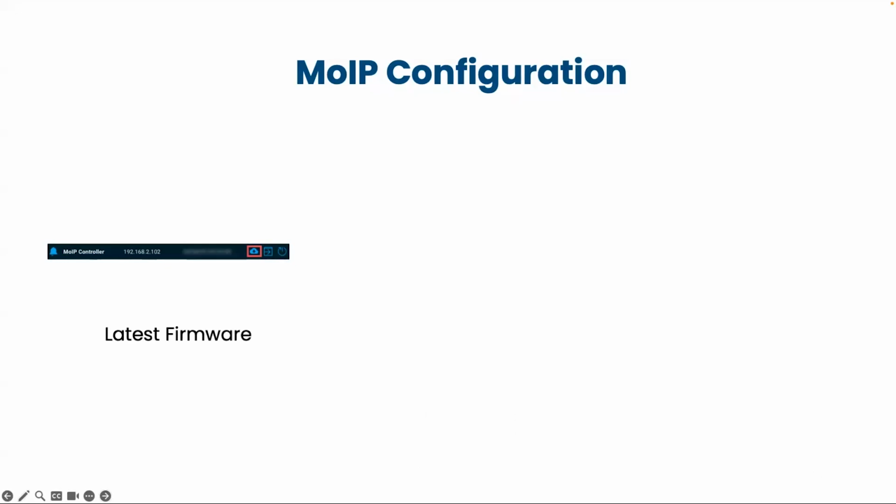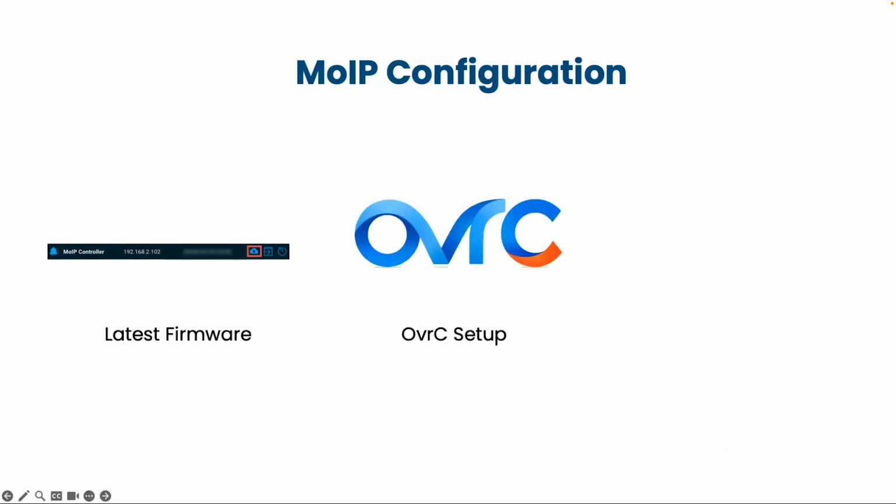After the controller is updated, then you're going to power off your MoIP switch and connect to the endpoints. Once the endpoints are connected to the switch and the switch is powered up, the controller will automatically upgrade any endpoints not on the latest firmware version. Once again, by endpoints, we're just talking about your transmitters, your receivers, and your transceivers.